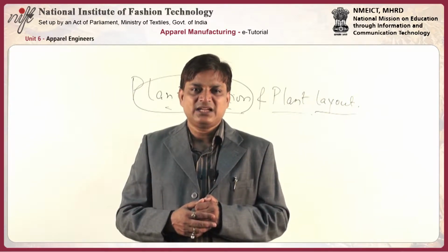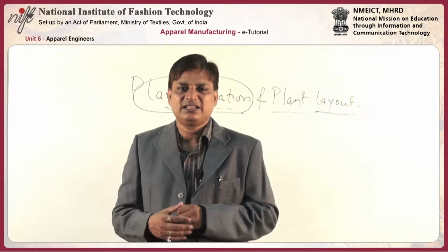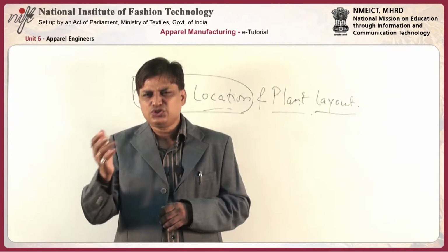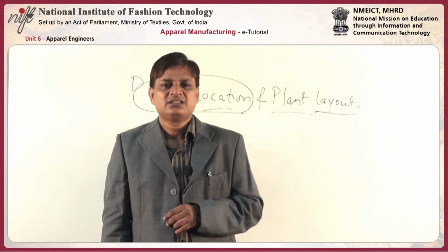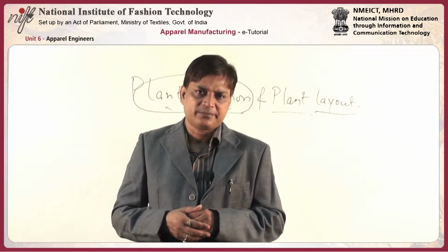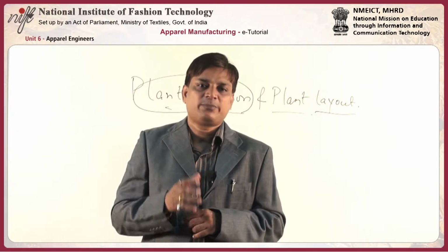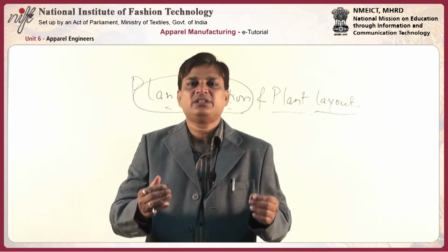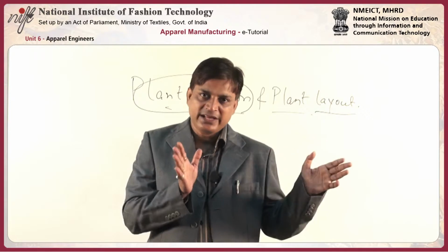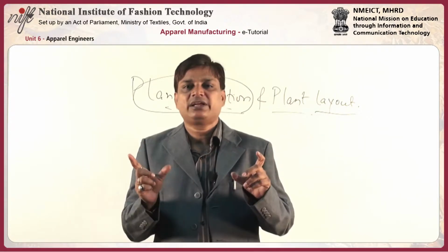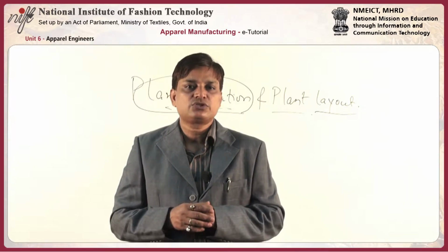We will discuss what the different steps are in deciding that particular land. Let's assume a case study where the land area is 1 acre. Now we have to find out the land coverage rule for that region. Usually it is 40% of the total area which can be covered. So out of 1 acre, 40% is the area which can be covered.